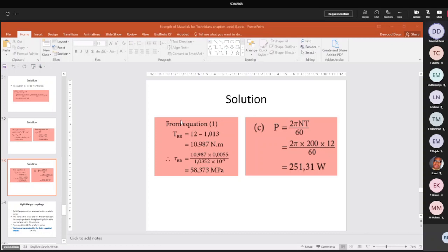One is what you call the longitudinal stress, which is PD upon 4T. How you remember it? Longitudinal is a long direction. So you'll have the big number here at the bottom, PD upon 4T. Stress circumferential or stress hoop. Another word for hoop is circumferential stress. Is PD upon 2T. Because the circumference is the smaller one. So that's how you remember it. So there's only two formulas, PD upon 2T, PD upon 4T. Okay? And see what they want and then you answer.